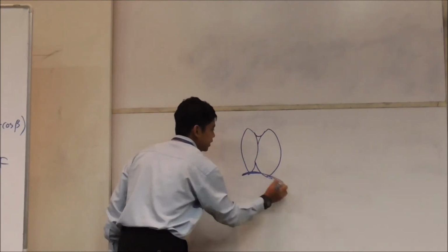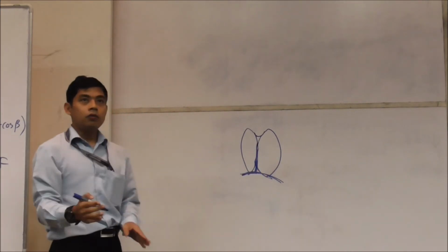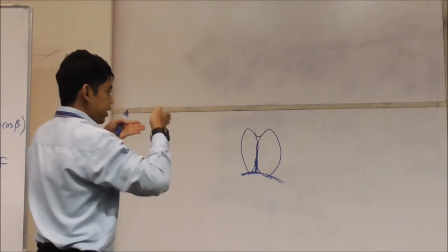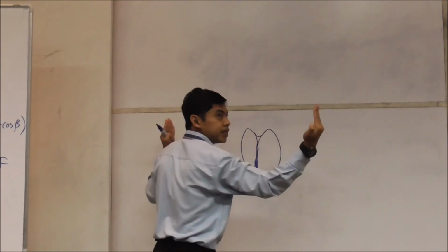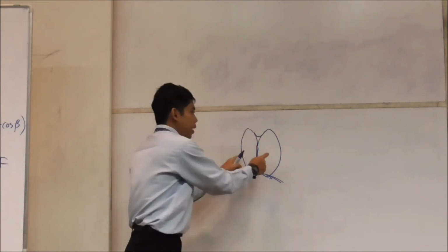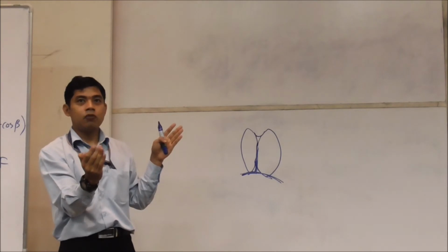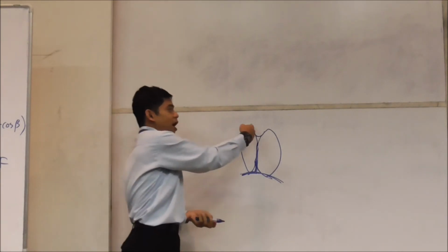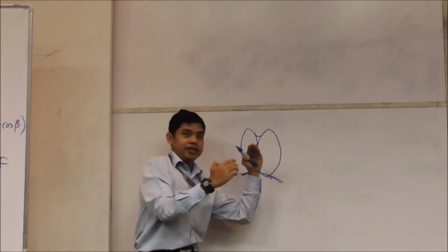Of course, this one is welded. It will look like this. You know why? The reason is when the water strikes, it will deflect to that side. So the next bucket is not disturbed by the reflecting water. Now you got the reason why it's like that. So that the next bucket is like that from here.